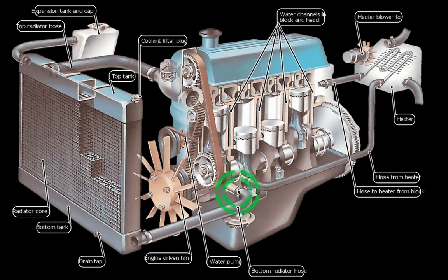And that's why you always need to have it. So it's not a good idea for those guys who ditched the thermostat to get some fake gains in keeping it cool. What they do is, let's say they have a leakage somewhere here, a very slight leaking point, so there was some evaporation happening and the water would reduce after a certain period of time, and the cooling efficiency was not so great. So some smartest mechanics tell them, why don't you ditch your thermostat, because it must have gone bad, and you will increase your flow.